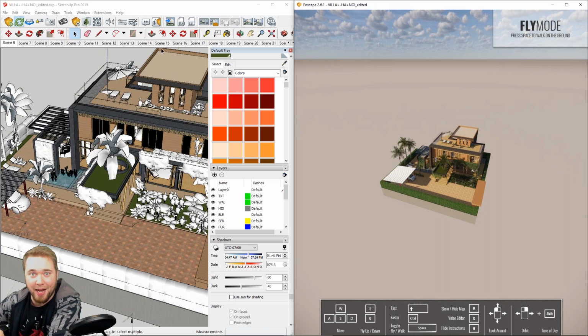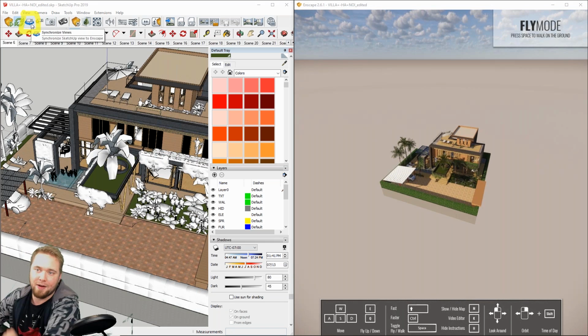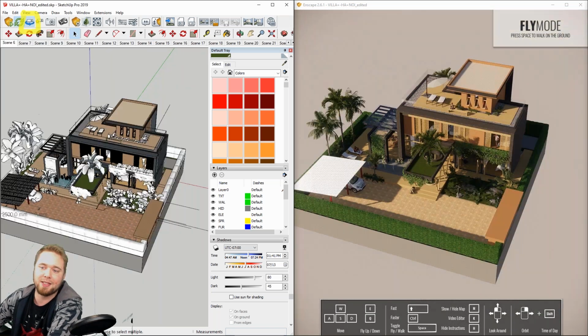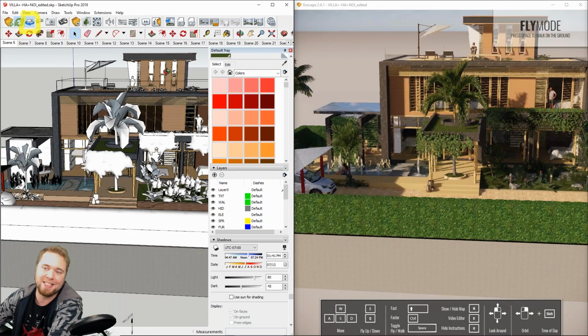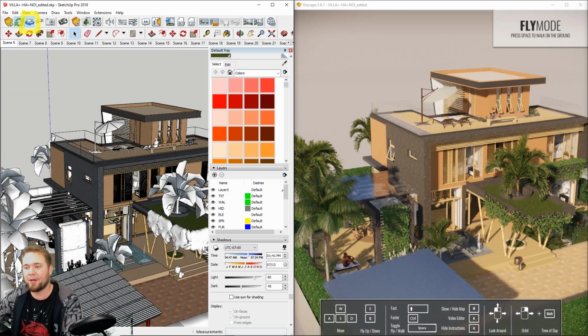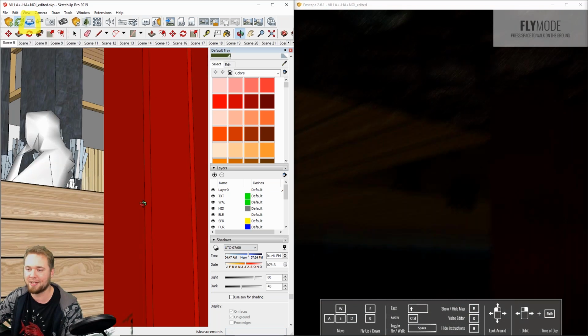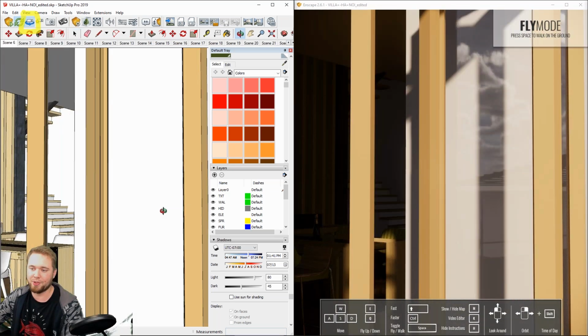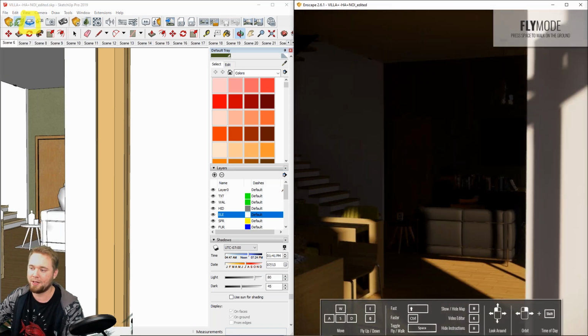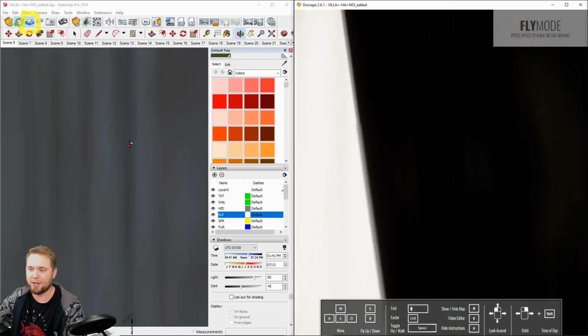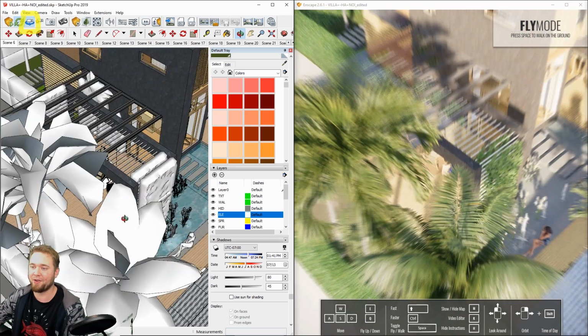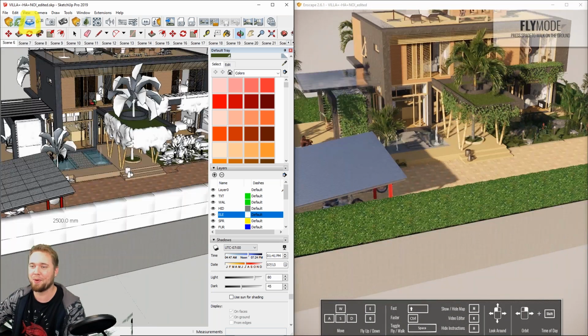If you don't want to get into movement in Enscape, you don't have to, because in SketchUp, we're actually able to provide you this button here. That's the view synchronization button, which essentially means you can tell Enscape to simply move wherever you are in SketchUp at the moment. So if you just want to stick with your already established ways of navigation in SketchUp, you're good to go with it. Enscape will simply follow your movement, and you don't have to learn anything new in that direction. So once again, and you see I'm not very experienced with navigating in SketchUp. I apologize for that.